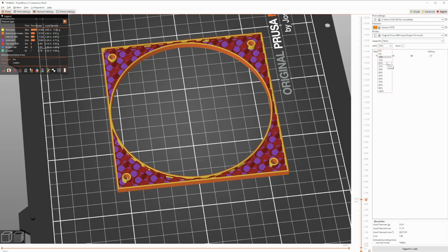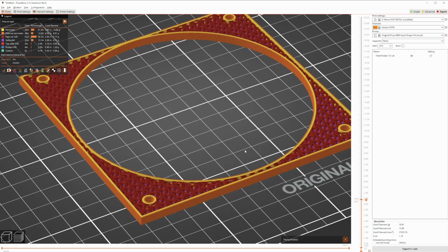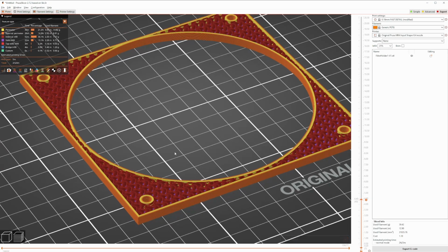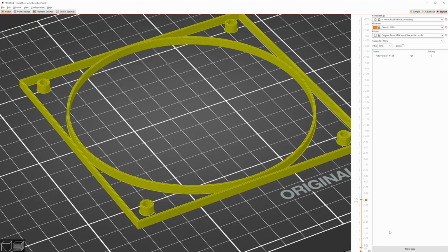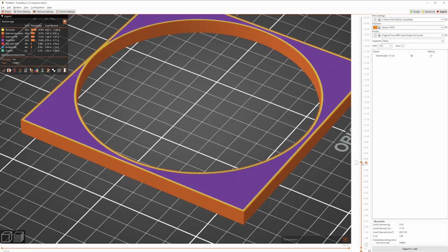And then we can also change how much infill percentage. So I was at 10 before, now I'm at 25. And you can see there's a lot more filament, which provides a lot more strength. But a lot of the time, this isn't quite needed. So I'm just going to leave it at 10% for now, and we can see how that turns out.